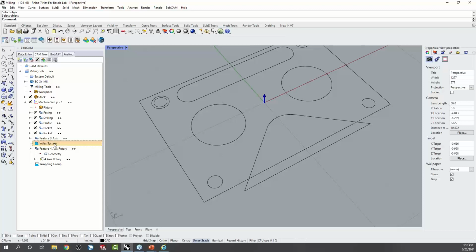So if I was making a bust or some other furniture leg on a rotary on a router, most of the time I like to do index machining to rough it, because 2-axis is faster than 3-axis, 3-axis is faster than 4-axis, 4-axis is faster than 5-axis, right?